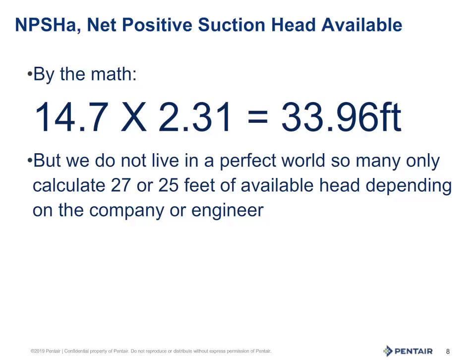What does this mean in a practical sense? This is why in the pump industry, we have set the standard of a maximum lift of 25 feet for a centrifugal pump, minus of course the friction loss in the pipe and the net positive suction head required factored in. But all this would be for another tech tip talk.